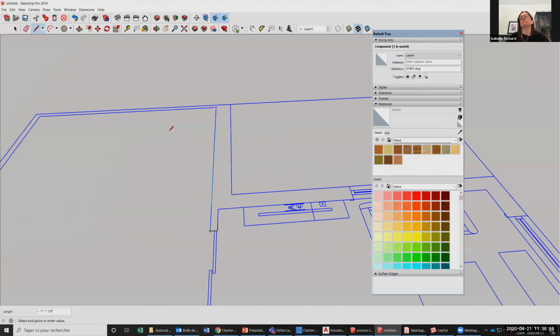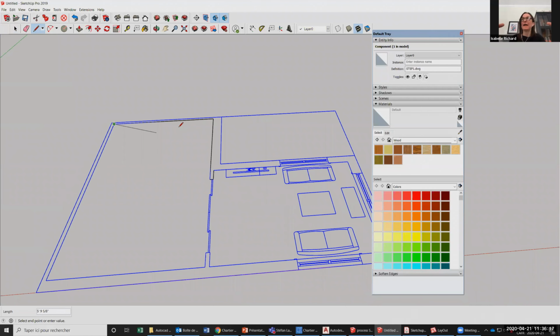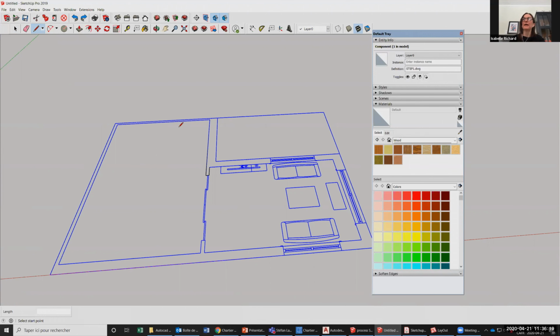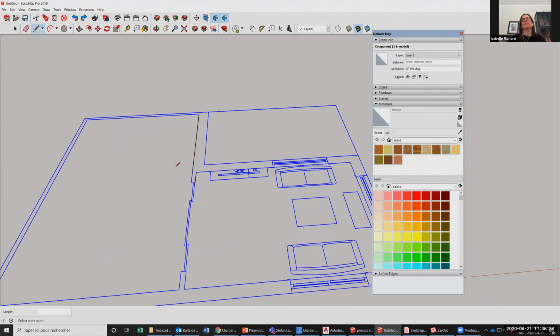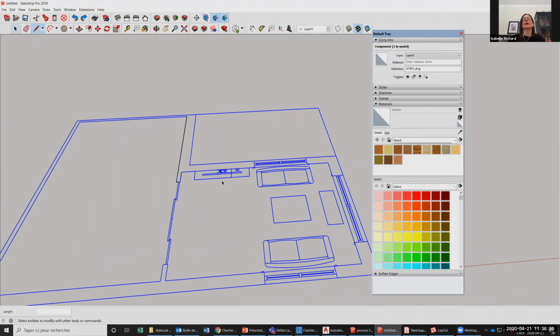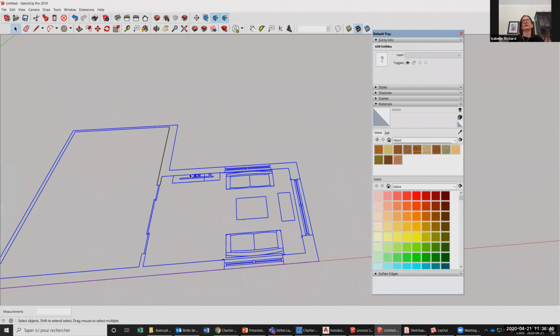Sometimes you have a drawing that is a JPEG, you import the JPEG, put it to scale, and then just redraw over the JPEG so you can make a floor plan out of it. But what I do normally is that I pick up the plan that I imported, I just explode it to make sure that they are all segments that are independent from the block, right?